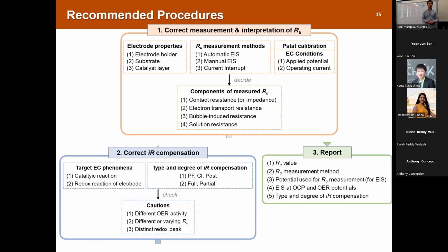So speaking of the alligator clip, it's better to use a platinum clip, which is the best, or a gold clip. Very conductive, doesn't form any oxide, but too expensive, right? Yeah. So the other option is a titanium clip, or even just a normal alligator clip made of stainless steel is fine as long as it has no surface oxide on it.